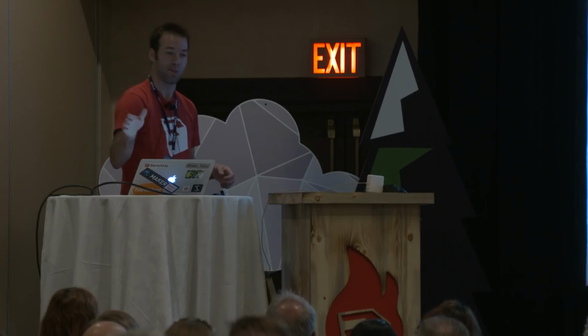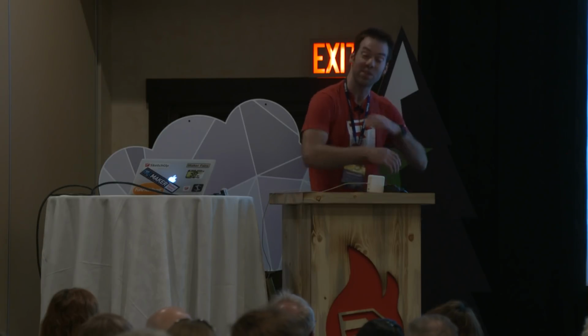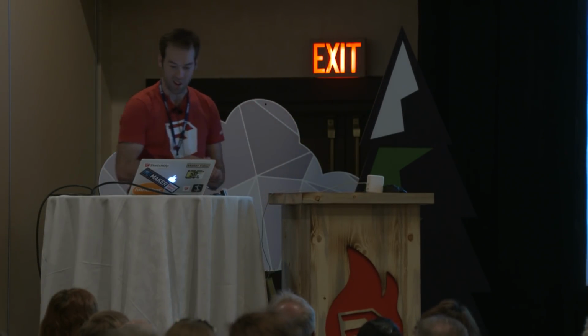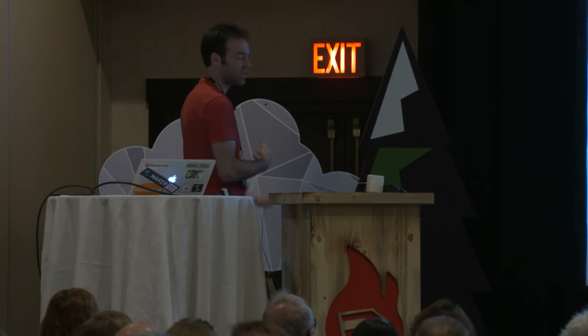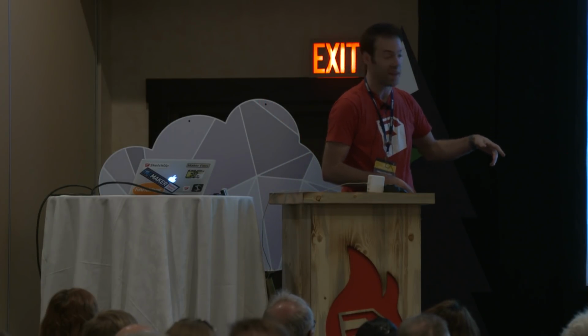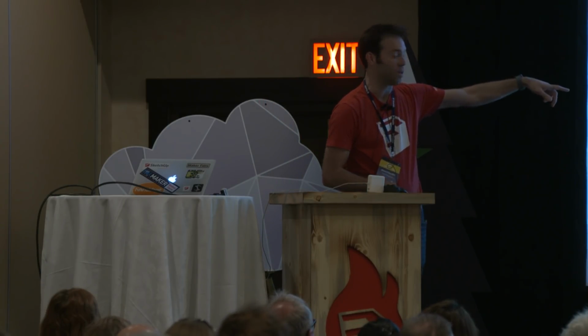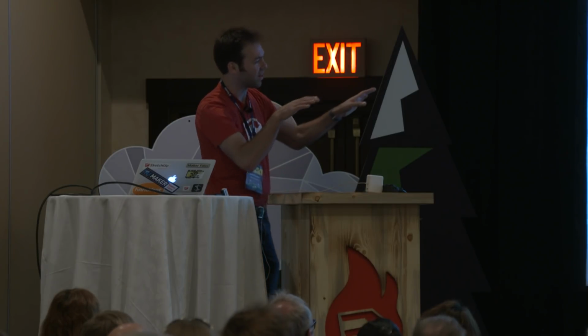I can't tell you how many people have emailed me after class and said, you showed me how to do all the stuff with guidelines, I'm mapping everything up, but every time I put a guideline on, I see it, and then it disappears, I don't know what's going on. So I'll show you how to fix that. Typically in any interior that I'm drawing, I will end up with lots of guidelines all over the place. This one here for the window, we're done with, we don't need anymore. If I was mapping out a complicated curved wall with a lot of angles, you end up with these dotted lines all over the place.